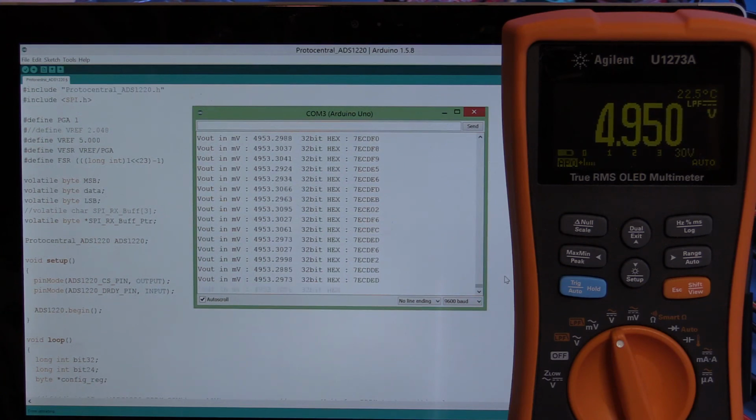We have plenty of other areas that we want to look at, one of which being one of the viewers suggested for the high voltage, for the high side FET, to get the extra volts above the standard supply rail would be to wind a few turns of transformer wire onto the toroid in addition to what's already there. So I've done that before, or similar to that, a long time ago, but what I will do is take the toroid off, unscrew it off the board, and put together a little video showing how you can do that, and we'll see how effective it is.